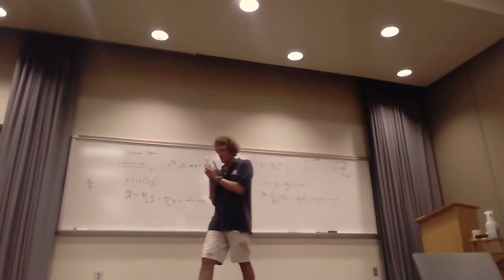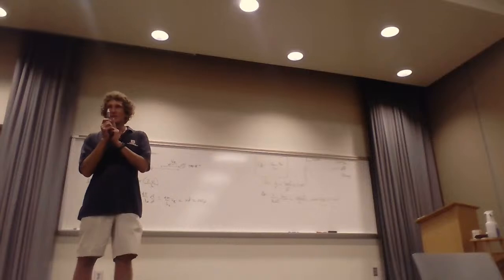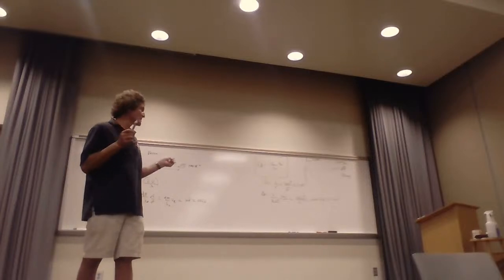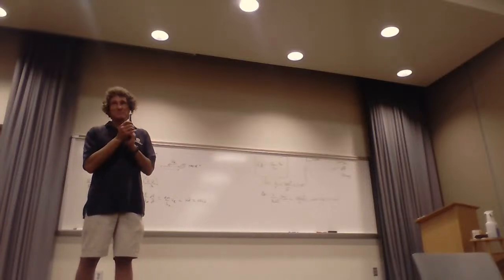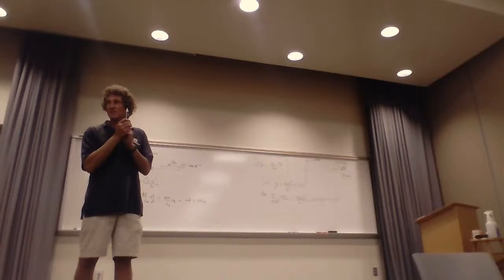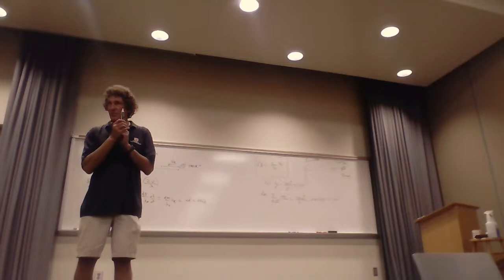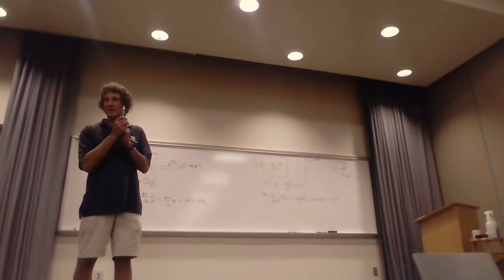All right, well, that works, but not well, because to get a 10 gigahertz oscillator that's exactly 10 gigahertz, and doesn't vary more than 6,000 hertz, it's ridiculous. I mean, just saying, a little bit of temperature usually would change it that much, right? That's an extremely small percentage. So what they do is coherent signal processing.